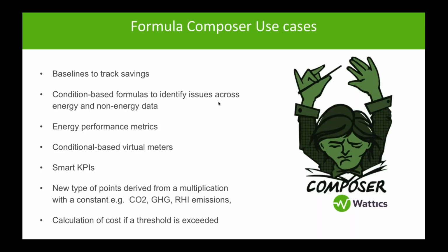There is a large number of use cases that I can think of for the formula composer. The formula composer effectively allows you to create formulas across meters, across data points, across weather stations, temperature sensors. Formulas meaning you can add meters, subtract meters, multiply data points, and do conditional analysis such as if-then-else, greater or smaller. A number of operators have been enabled, and as we go along, we will enable other operators such as maximum, minimum, or AND, in order to have nested if-then-else. But here I've written a few of them.